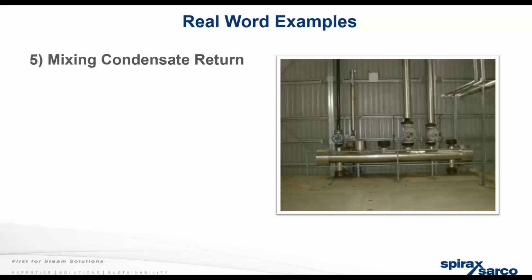They look great. In these instances, we're bringing back pumped condensate, flash steam from steam traps, high pressure condensate, medium pressure condensate, all to a nice header. And then we're forcing all that condensate back into a receiver tank, which is right next door, because it looks pretty, I guess. And we're mixing those condensate lines, which we're treating as hot condensate lines.